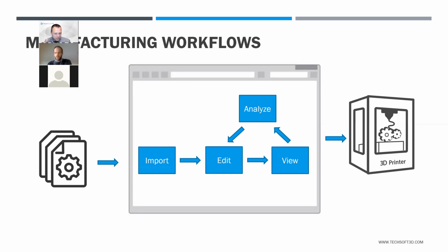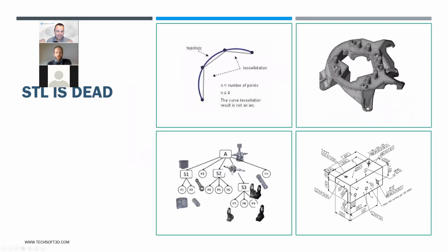But let's focus in on just that CAD import for a minute. We'll be looking at each of these different components. So if we look at STL files, which we all use, there's a ton of them out there, and just for historical reasons, we're used to reading those and using them for 3D printing. But really, there's some inherent problems with STLs that we want to draw attention to, and actually say, because of those problems, STL is dead.